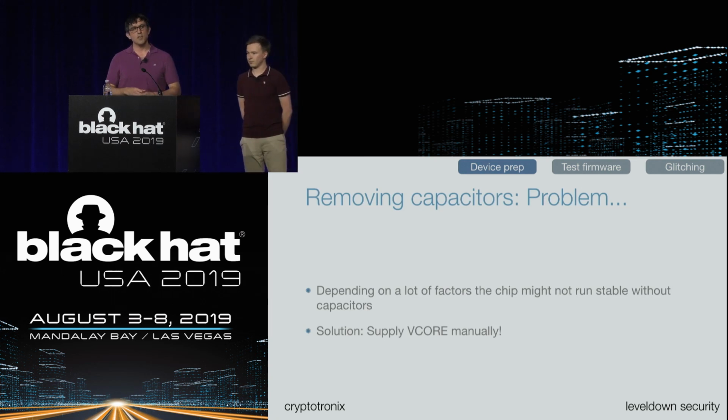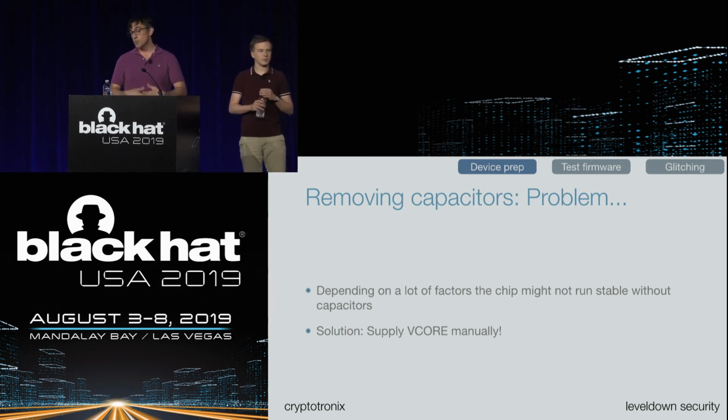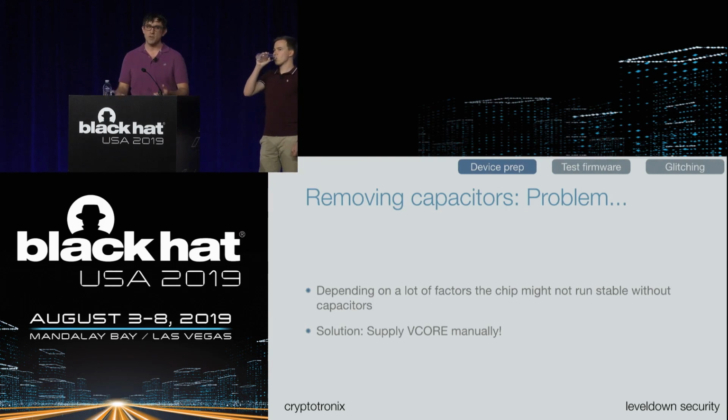However, this is the point where trying to do a glitch attack is also, I should say, more art than science. There's a lot of factors that can cause an issue, one of which is if the manufacturer is recommending that you add capacitors to make your system be more stable, removing them makes them more unstable. Some chips may not boot without them. So it kind of depends on the chip. But yeah, if you take those out, it may not run stable.